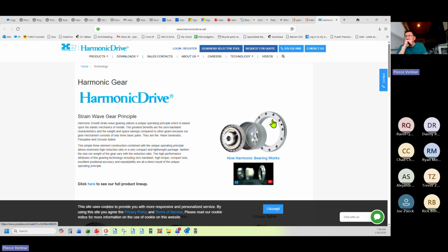Yeah, okay. Perfect. Yeah, exactly. It's an ellipse equation then. That's right. Thanks. And so, again, depending on the number of teeth on this interface between the OD and the ID, you get different ratios. Typically on the harmonic gear sets that I've seen, 70 to 150 is very common on a single reduction harmonic gearbox. Did that answer your question, Dan? I think so, but I'm going to still Google it and look for some more information. Okay, very good.